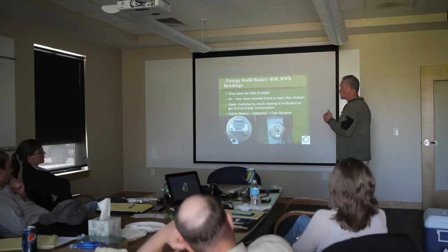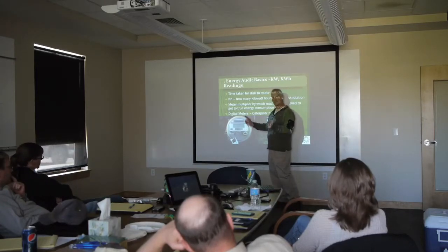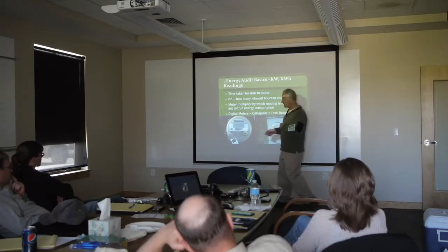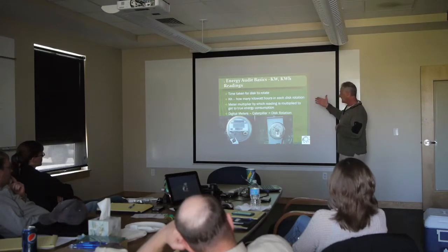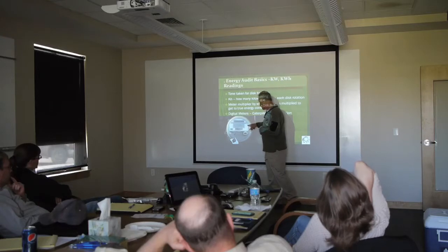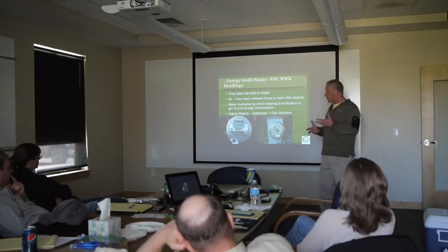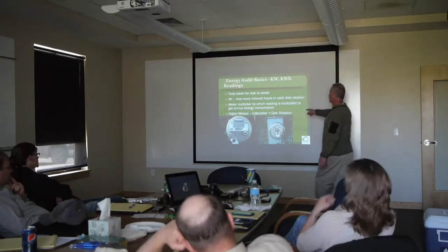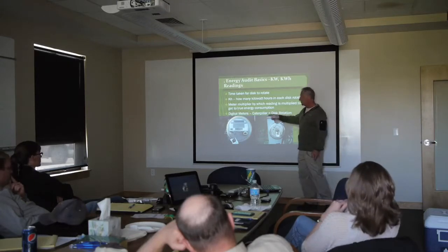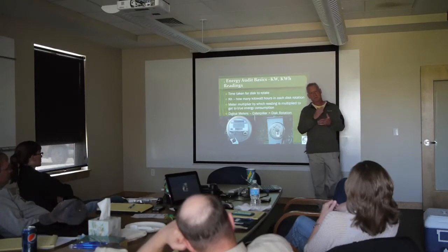And they'll switch from kilowatts to kilowatt hours in the same meter. There's a meter multiplier. One of these little numbers here someplace will have the multiplier. Then you have your K sub H, then you multiply that by the meter constant.